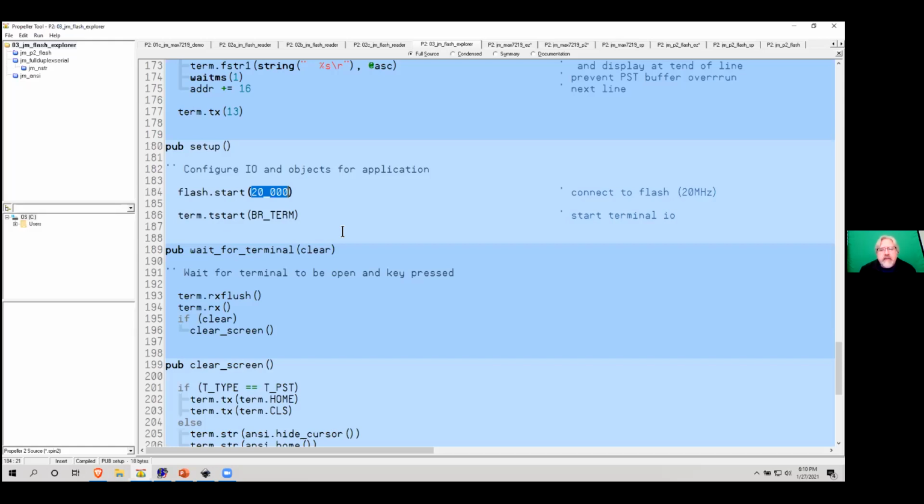On the laser tag, the first version, the P1 version, the P1 takes 32K for program space. So I put a 64K EEPROM in the design so that I could write to the upper 32K the parameters about the laser tag weapon.